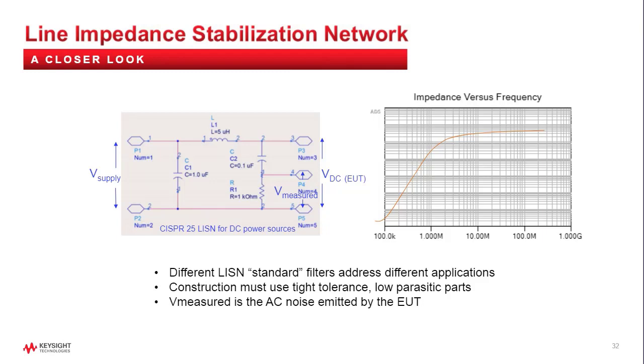Yeah, so part of it is, it's a little bit of a trick question if you don't know wire gauge sizes, and some people have a pretty good feel for them, and some people don't. But a 20 gauge was my guess when I first saw this question, and the correct answer is number 12. And you think about 12 gauge wire. 12 gauge solid wire is about the last solid wire gauge you can actually conveniently bend with your fingers.